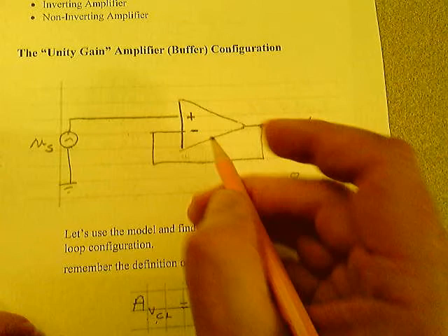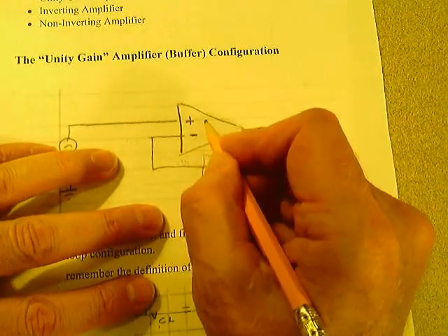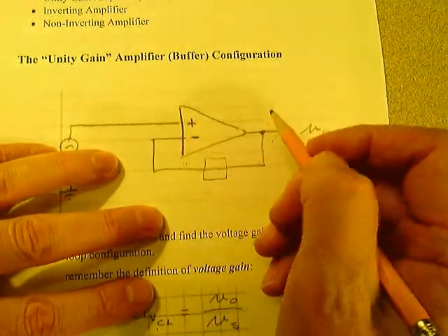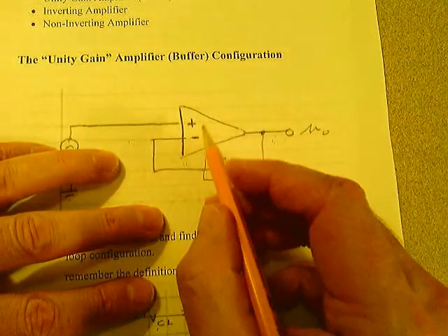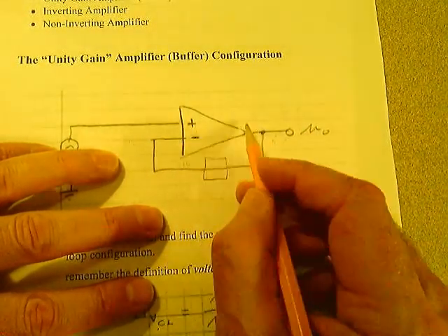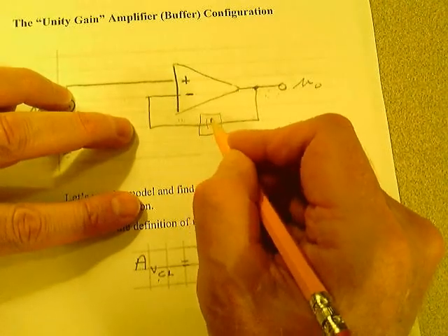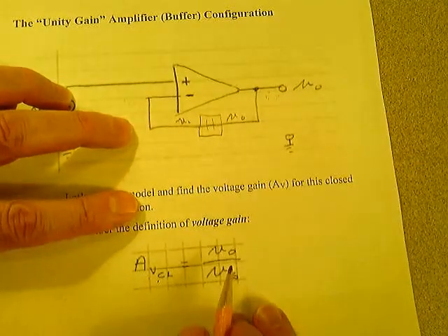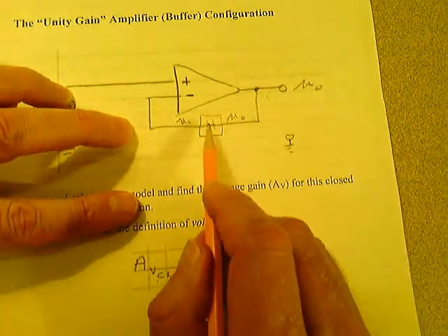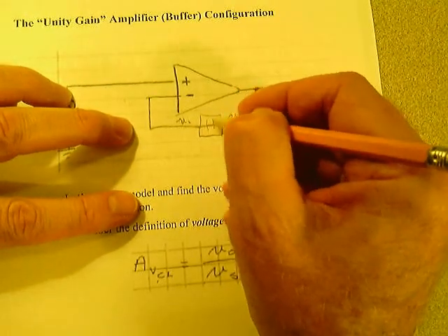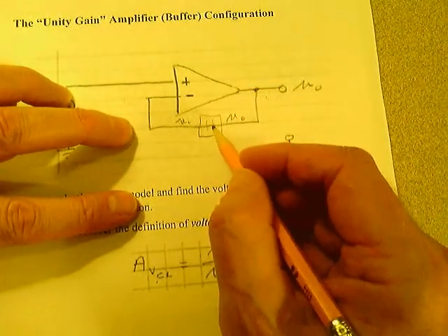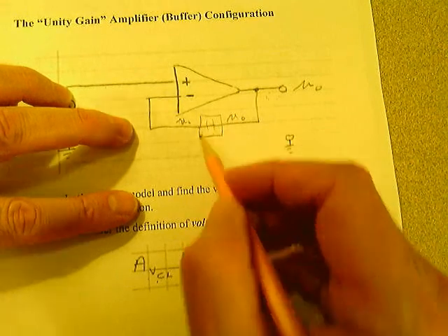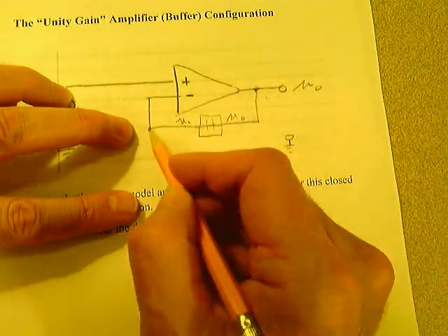Well, look. You know what this is up here. This G up here is the open loop gain. This is the closed loop path. So what's the open loop gain? It's A0. It's infinity. This is all going to cancel out here in a minute. But how do you get H here? This is H. Well, if you have V out here and you have V out here because it's just a wire, what's the ratio of V out over V out? It's 1. So you can put a box here and put the block diagram for that. It's just going to have a box there with a 1 in it because you're feeding 100% of it back.